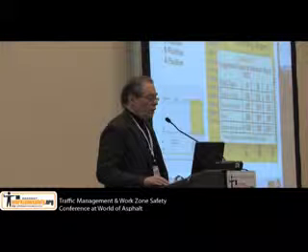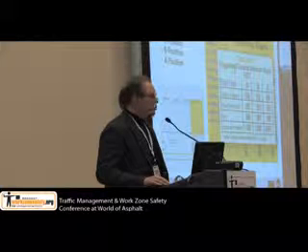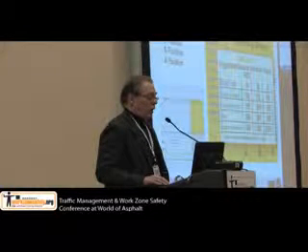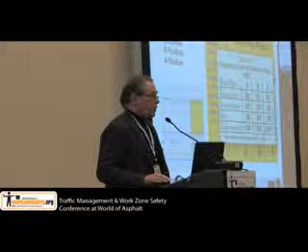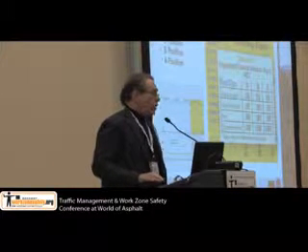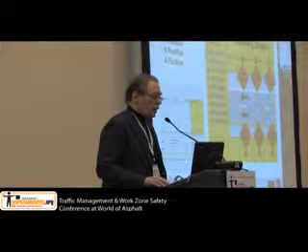What does the MUTCD use to determine the suggested distance between these advanced warning signs? It uses the type of road: urban, rural, and expressway. Now, obviously, we know that some of these roads are going to be faster than others, but the MUTCD itself actually employs this as the means for determining the spacing.